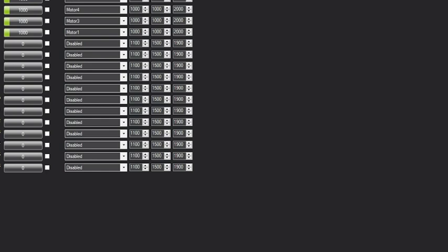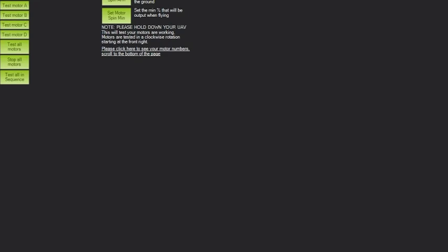So to double check that before we continue on, come to optional hardware. You'll need to be plugged into a battery or an XT60 wall adapter to check on this. You can come down here to optional hardware, and there's actually a motor option. So once you're here, you want your throttle to be pretty low. I wouldn't go higher than 5%. It should be plenty. You can just go through and just test each motor, and it'll spin it up for a few seconds. And just give you that general idea of where it's supposed to be.